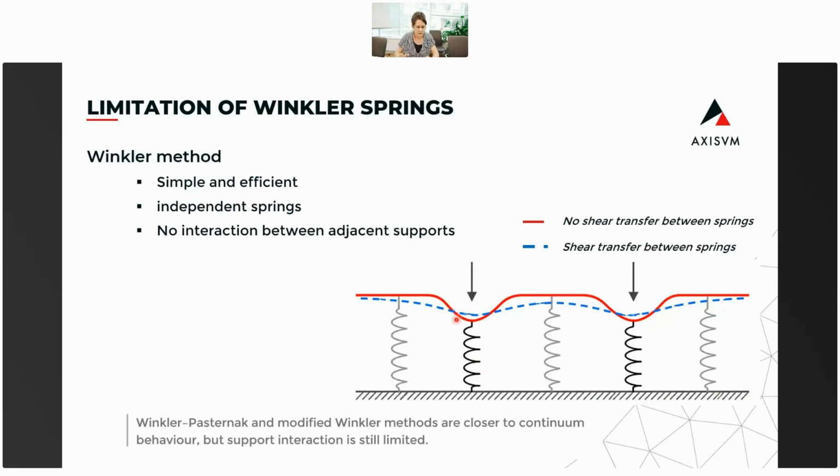The soil behaves as a collection of independent springs rather than a continuous medium. Pasternak and modified Winkler methods are closer to continuum behavior, but support interaction is still limited compared to a 3D model. This simplification is often acceptable, but its limitations always have to be kept in mind.